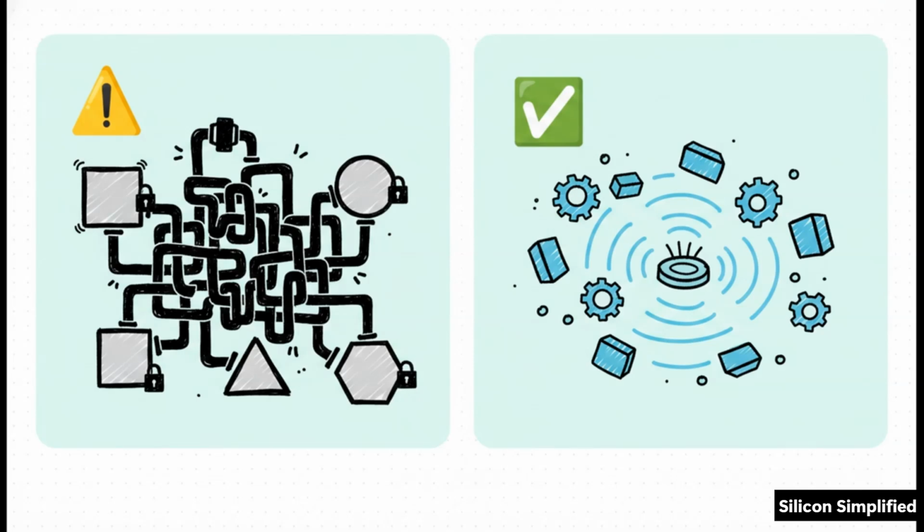It is notoriously frustrating when you're trying to access data from inside a sequence, because it forces you to use those messy p_sequencer workarounds. On the flip side, looking at the right, the underlying UVM resource DB uses straightforward string scoping. It can be accessed from absolutely anywhere, even non-component classes. It truly unlocks architectural freedom.